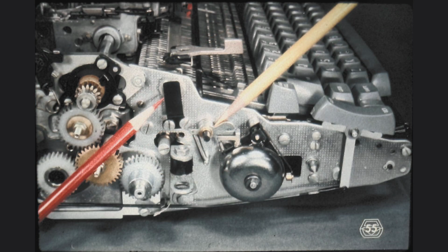The whole procedure might once again be considerably different or simpler if you happen to be working on an older style or even an 11-inch machine. In this case, you do not even have to worry about the margin rack return spring. The leaf spring indicated by the red pencil takes the place of the compression spring existing on newer machines. We leave it up to your common sense to cope with these variations in design.